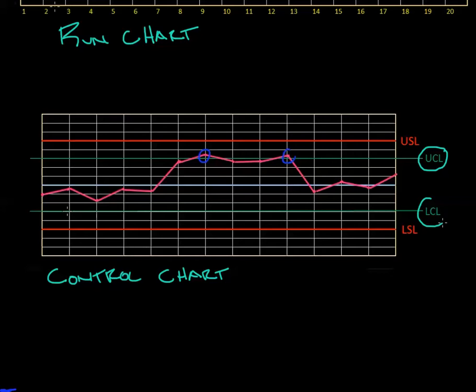And in the video on control charts, I explain how the upper and lower control limit represents where the process should be running, or it represents the variation caused naturally within the process. And if you find that your process is running outside of the control limits, it indicates there's a special cause and there's a need to investigate why that is out of control.